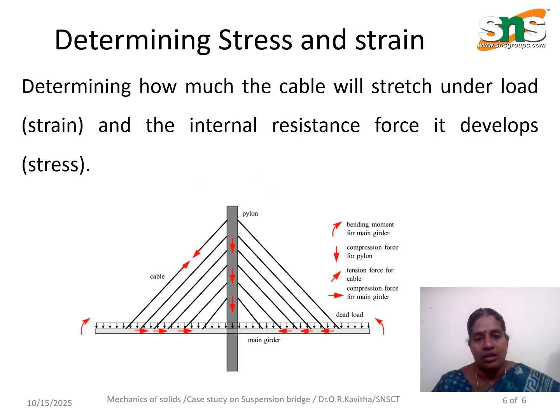Next, we have to determine the strain and the stresses under the different types of loads. Here these are the different components. You can see this downward force is nothing but the self weight, and these cables are subjected to the tensile force. The deck slab, that is a girder, will be subjected to bending moment. And this is the main girder.